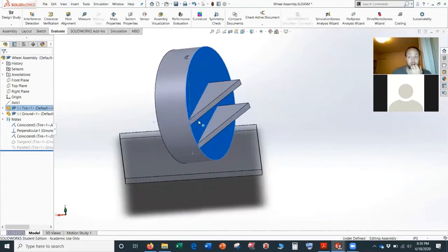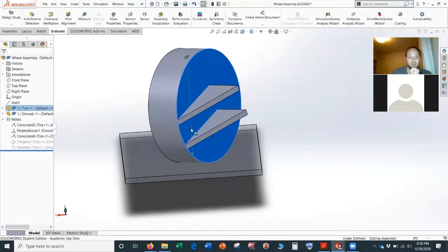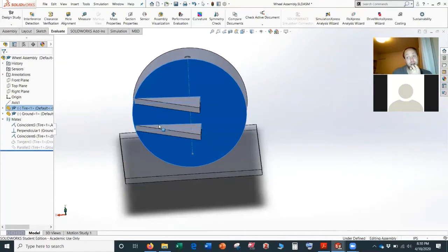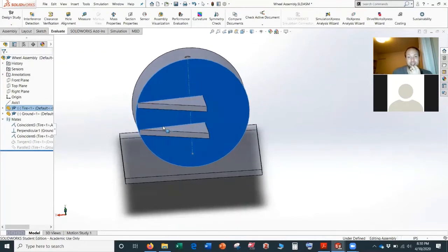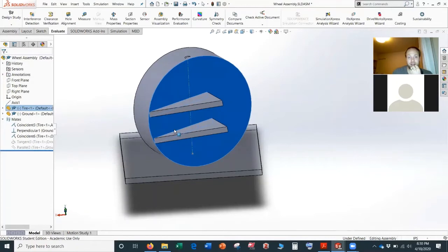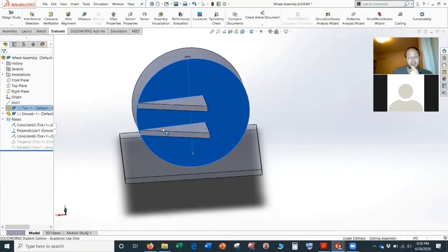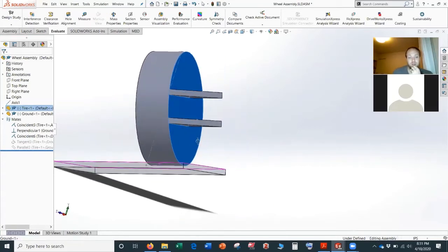kind of is allowed to go up. It's actually kind of going to allow your car to sink down a little bit, which will kind of lower its overall potential energy, right? So my intuition here, which I don't know if it's right, is that this would be slightly unstable. It seems like you wouldn't have as much of a natural steering return, whereas before we knew that having some kingpin inclination and the scrub radius, the tires dug into the ground, and so it made them go straight. Here it almost seems like the opposite effect. So that seems not advisable of a thing to do.